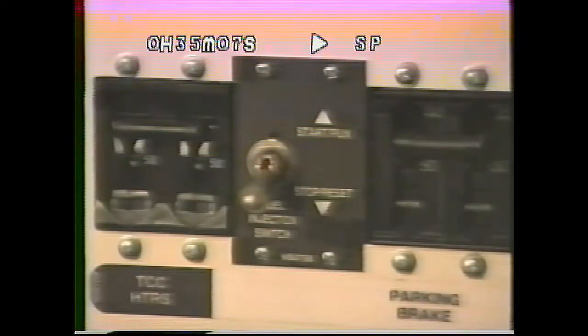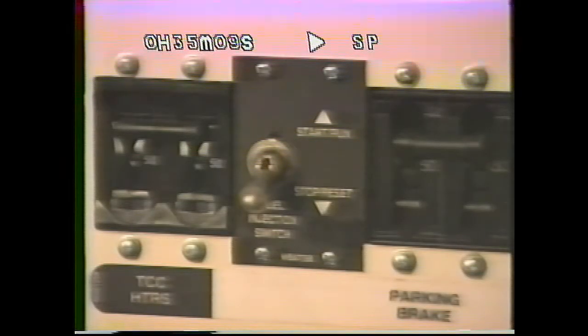Oh, and don't forget, if the engine has been shut down for an extended period of time and the engine block is cold, you should open up all the cylinder test cocks and crank the engine over a revolution or two to clear out any fluid that may have accumulated in the cylinders. On the SD-80 Mac, you must leave the fuel injection switch in the off position when doing this procedure.